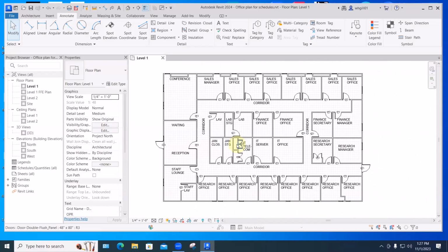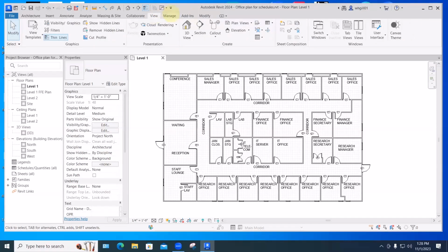So let's make the schedule now. You know, a schedule is like another camera. The cameras are all managed here in views. We go to View, here, Schedules. Anyway, somewhere in your View, Create Model tab, and Schedules.